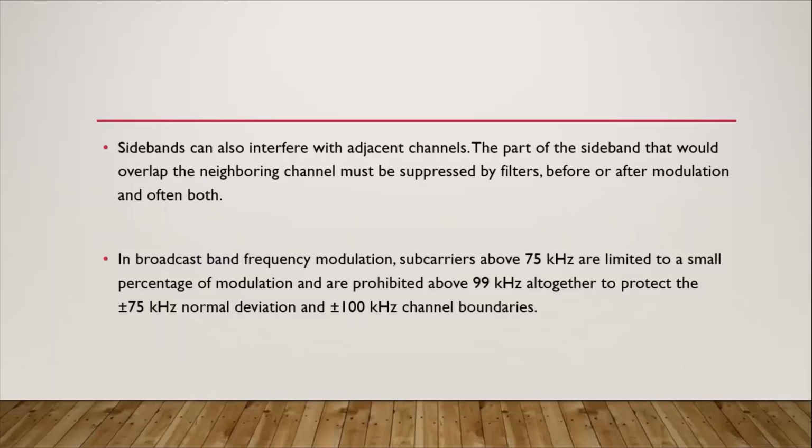Okay? In broadcast band frequency modulation, subcarriers above 75 kHz are limited to a small percentage of modulation, and it is prohibited above 99 kHz altogether, to protect the normal deviation of plus or minus 75 kHz.